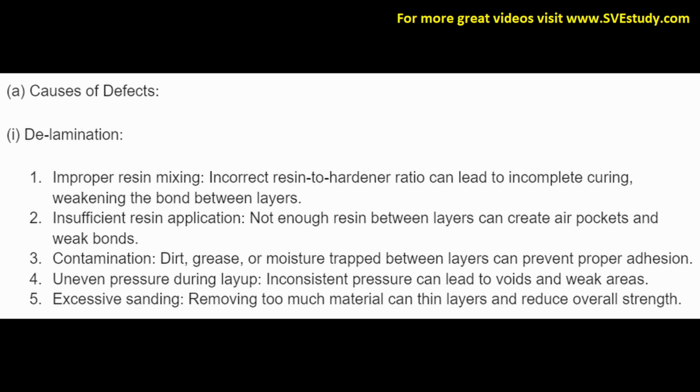Causes of defects. A. 1. Delamination. 1. Improper resin mixing. Incorrect resin to hardener ratio can lead to incomplete curing, weakening the bond between layers. 2. Insufficient resin application. Not enough resin between layers can create air pockets and weak bonds.